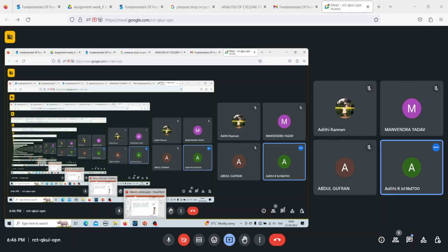So in case of a screening process, the cut point diameter or DCP, as I told, is the diameter of the particle which has the same width as the screen opening. So if you have multiple particles and you're passing them through a sieve, the sieve or screen will have tiny openings or pores. So when the diameter of the pore becomes equal to the diameter of the largest particle that you're sieving, that is known as the cut point diameter. So the screen opening is equal to that of the particle size. That is the definition for a screening process.